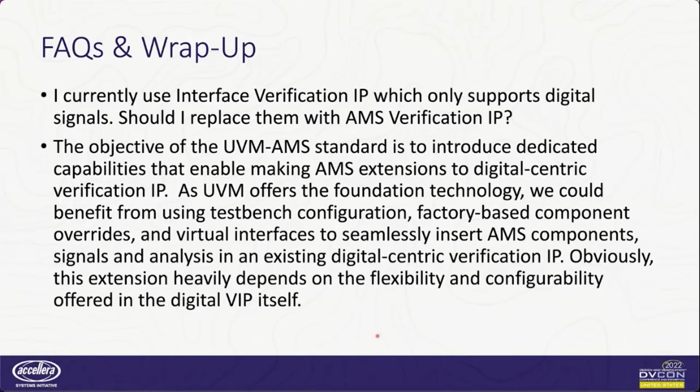All your test bench data is still valid, because all we're doing is adding in the MS bridge that allows the use of a proxy if a proxy is needed, or passes the signals through the analog resource to the corresponding ports, and allowing the use of analog ports if that is needed. So that's the whole purpose of UVM AMS, is to make a very easy transition from a digital VIP to a mixed signal VIP, and still staying in the UVM context.